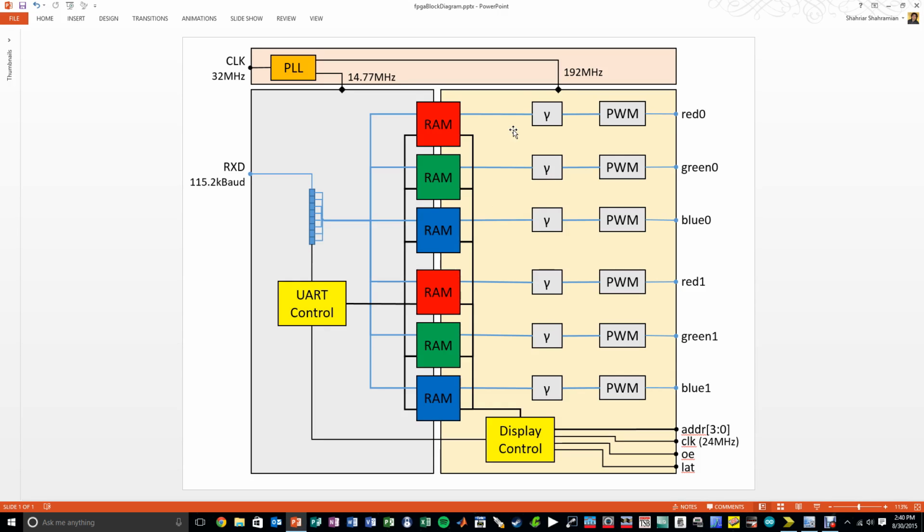And if you look at the Arduino codes, for example, that are available to drive these screens, they often write code at a very low level in assembly, in order to increase the timing margins and have a very efficient code that's really close to the hardware of the microcontroller, in order to do this inside a typical microcontroller that you can buy, like an Arduino. But in reality, any serious display driver is never done directly in a microprocessor. It's always done either in a specific ASIC designed for driving displays, which would look something like this, or it would be done with an FPGA. This is why this approach is the better engineering solution for a scalable solution, as opposed to using something like an Arduino.